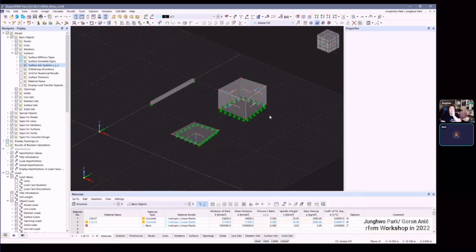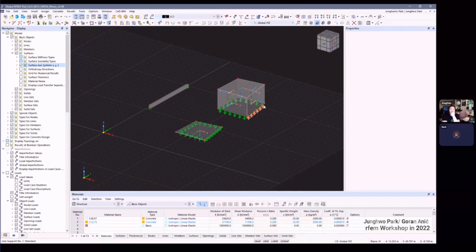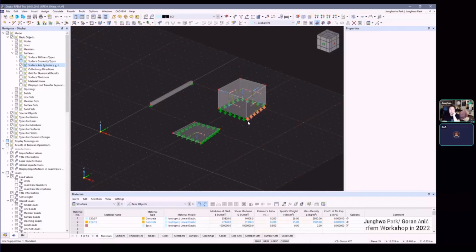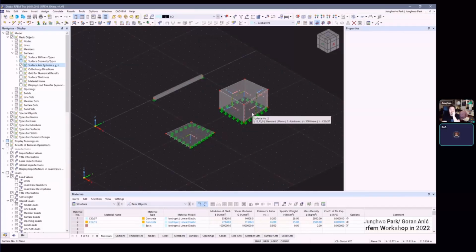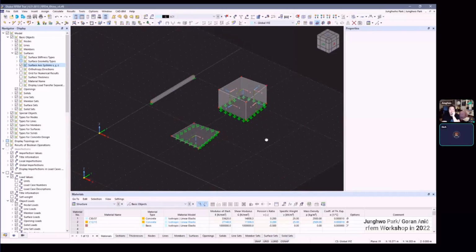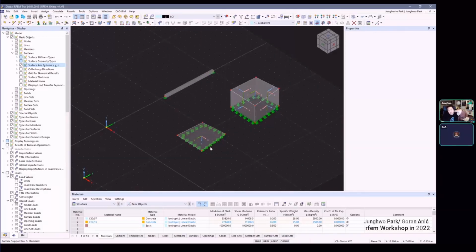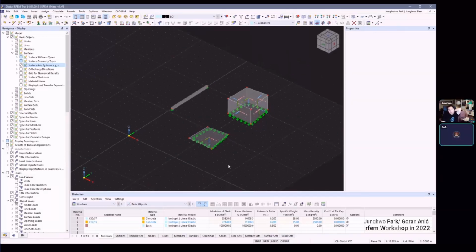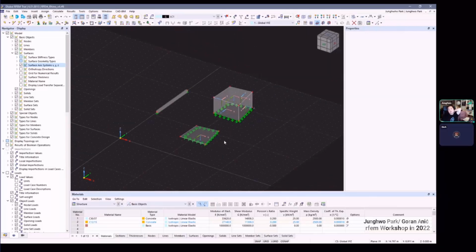If you make a classical design, floor by floor, statical calculation from some building, then you can put this spring constraint regularly, and you will get the forces which you will transfer to another part of the building, and at the end you can create the complete model of your house with the spring condition for checking the foundation. So if it's a big project, you do substructure analysis, floor to floor.